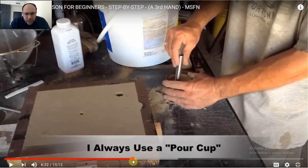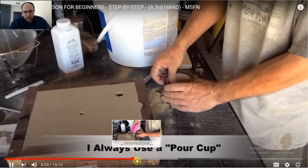So instead of targeting this opening directly, he has prepared this cup, and he's gonna keep on pouring the melt into the cup, which will smoothly go through this sprue to fill the mold cavity here.